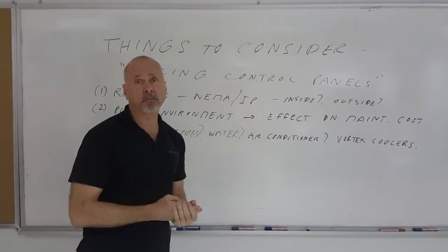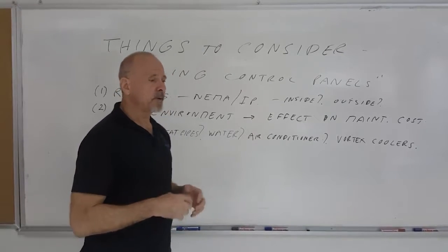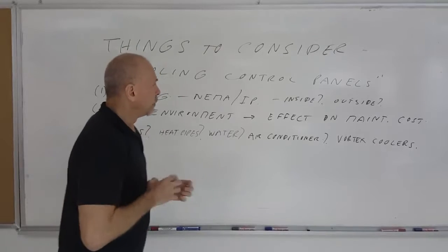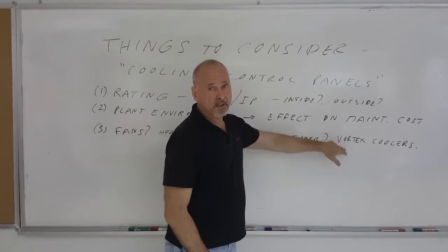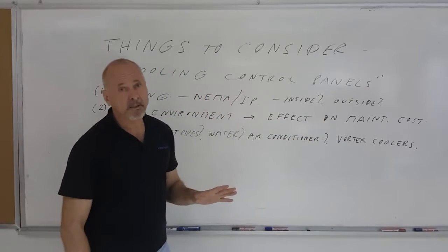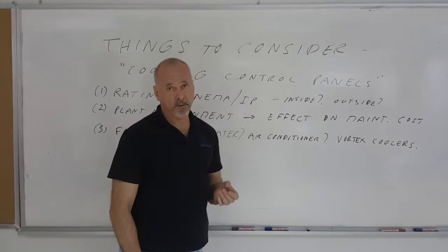There are no filters to replace. They keep the panel at a slightly positive pressure to keep out a very dirty environment. So when you get to a very, very dirty environment, that's when you start looking at VORTEX coolers, because the maintenance savings offset any increased energy cost of utilizing the compressed air.